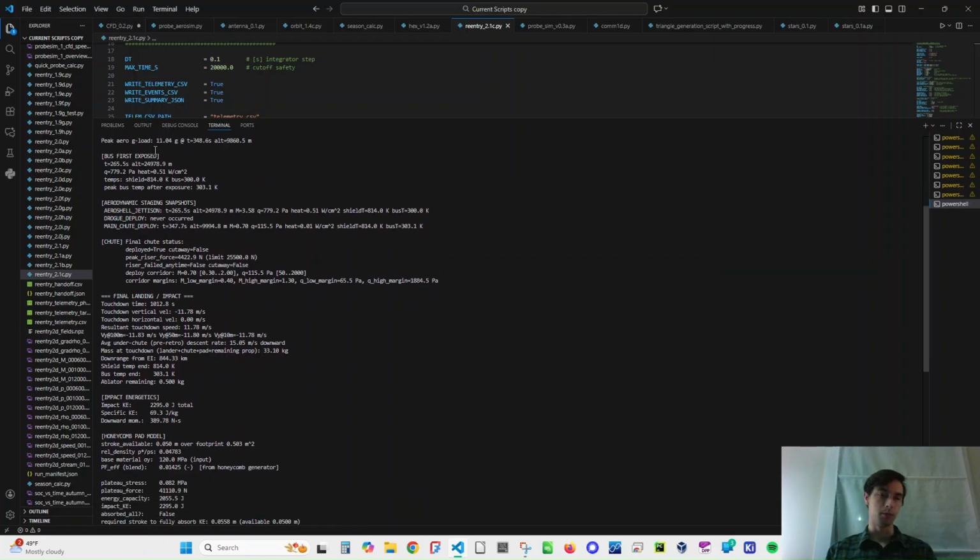And then this is for when we deploy our aeroshell, because we first deploy the top part and then the bottom part. And there's a couple of reasons for that. It's mostly reducing mass and things like that. Because if you deploy the bottom too fast, remember, this thing is light and has a really big CD and decent sized area.